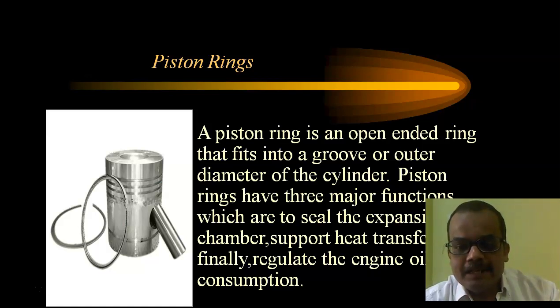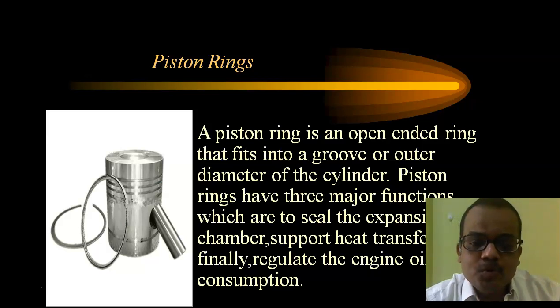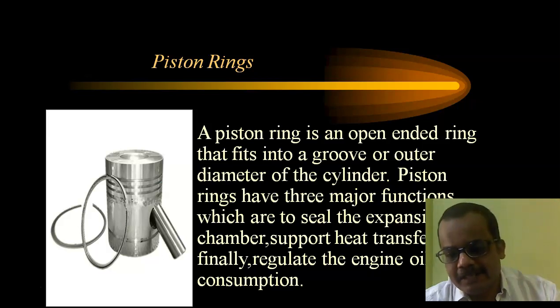The compression ring seals the expansion chamber. After the power stroke, whatever gaseous force is produced should not move out of the cylinder. That is the function of the compression ring. Whenever you encounter a problem where you are not getting pickup on your bike or moped, the first problem might be that the compression ring has worn out. So before opening an engine, mechanics used to change the compression ring. That is the function of the compression ring.